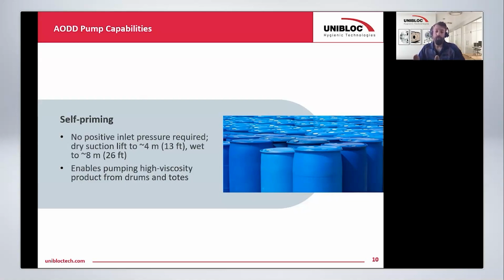And so you won't always need a bigger pump to get the flow rate you want. Sometimes you just need a larger inlet connection, because that makes the suction lift easier. So that's a good tip. Keep that suction distance as short as possible, since that's the harder thing for the pump.